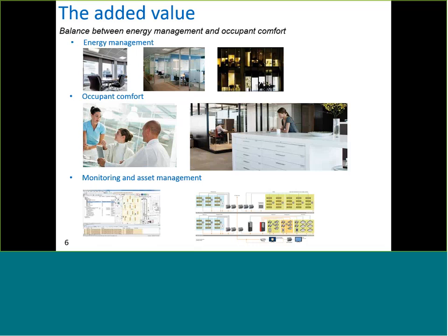Added to this is the occupancy comfort, so that the lighting control system, as much as it's trying to achieve its primary goal of energy management, is not being disruptive to the occupants and allows them to be as productive and efficient as possible. Most HR departments will tell you that any 1% increase in occupants' productivity will easily outstrip any gains from efficiencies in energy management.